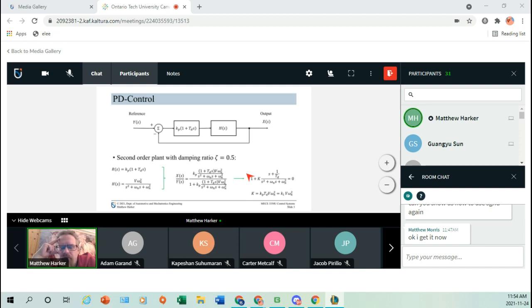So we have the monic polynomials in the numerator and denominator, and that just means that our k that we're varying is equal to either Kp TD with the system gain and the natural frequency squared, or, in terms of the Ki, Kp times TD. That's basically just saying we're varying the gain of the system. It just means if you want to find specific values, you have to remember that this k means this or this for our rules.